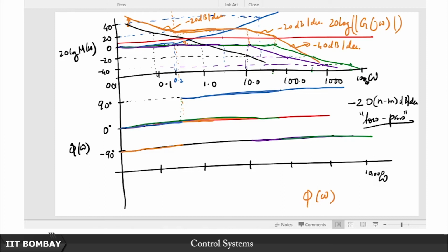So we have this at low frequencies we have minus 90 degrees. From the first break frequency onwards at point 2 we have 0 degrees all the way up until 10. At 10 what happens now? Now you see again this purple line brings it back to terra firma. So this is going to be the purple line's contribution, it is going to pull it back again.